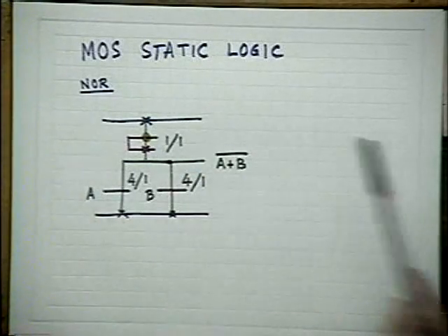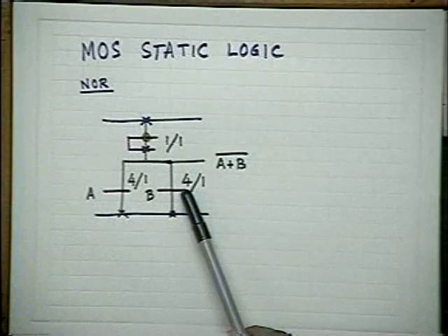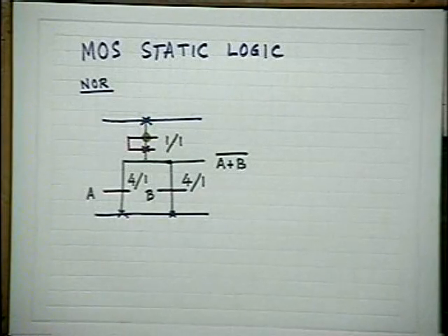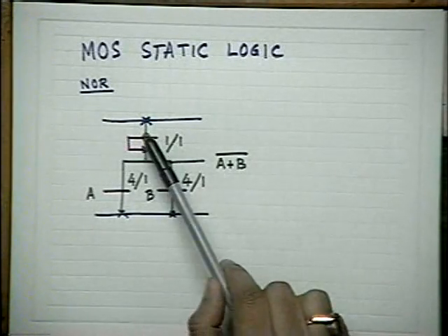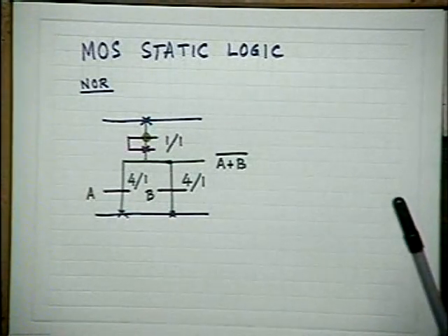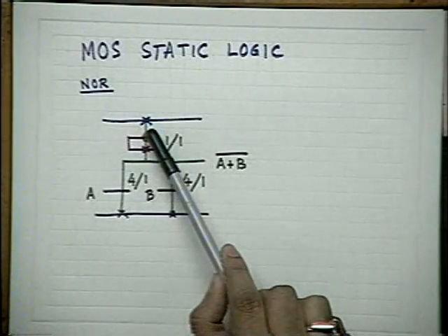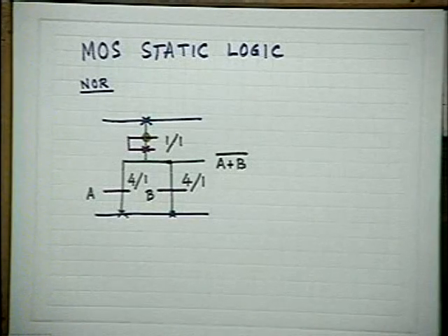Accordingly, you see that this is the nMOS NOR gate using HMOS, where HMOS has an enhancement mode driver whereas a depletion mode load. That yellow dot around this intersection indicates the transistor here is not an enhancement mode transistor, it is a depletion mode transistor.